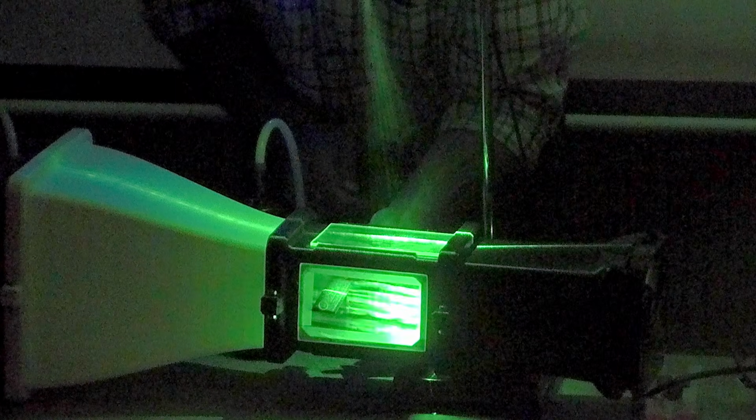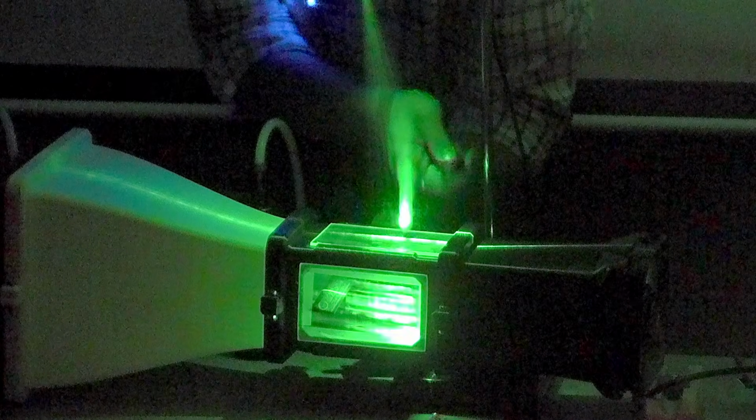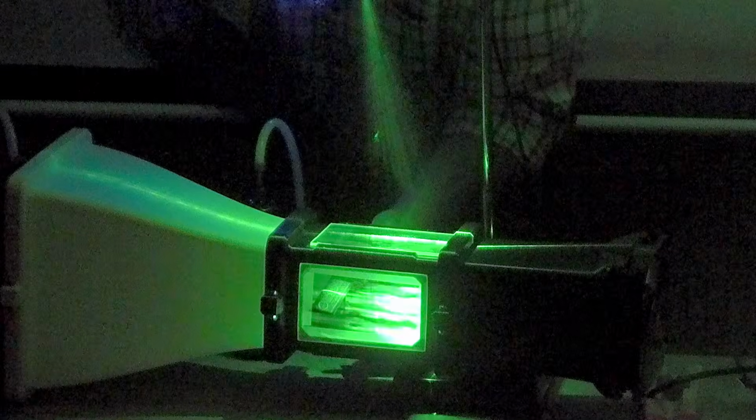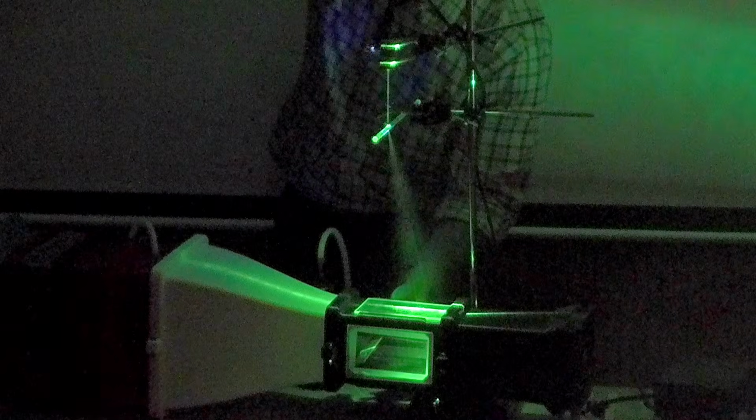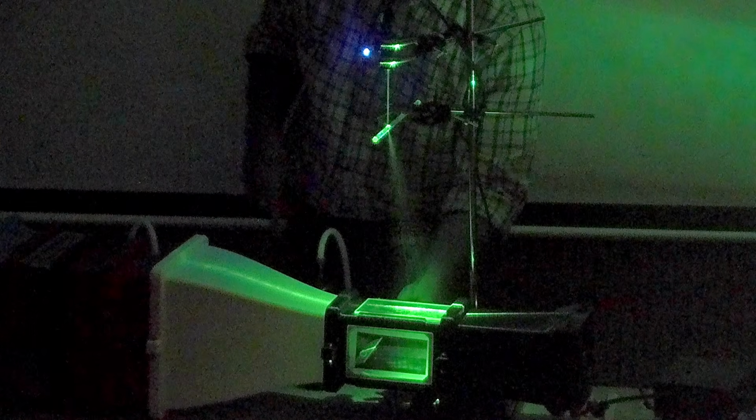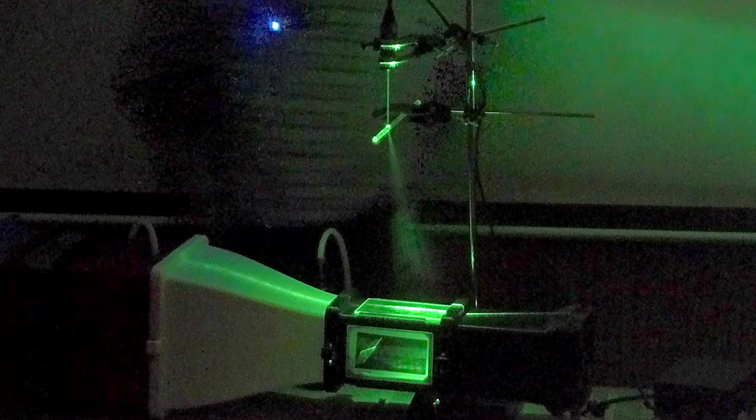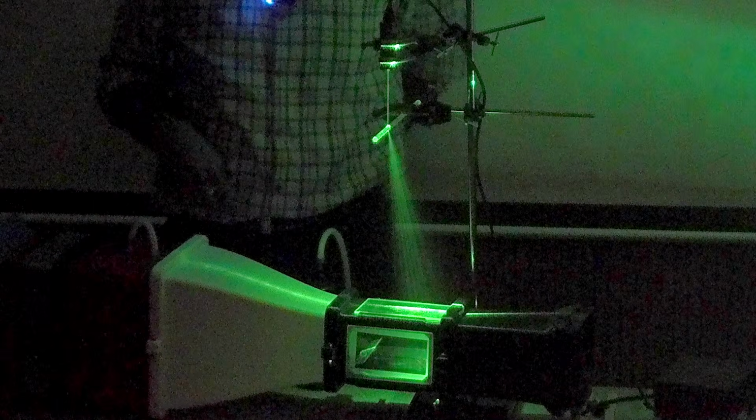separation happening. Now another thing that I want to point out is, if you look at the downstream wake of this flow, the moment I increase the angle of attack, you see this flapping of these lines. Okay, this flapping of the lines is actually known as vortex shedding.